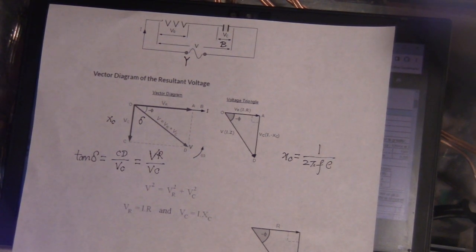Then what is a good capacitor? A good capacitor, based on the Nichicon data, is what? UFG is better than UFW. UFW 50 volt capacitor has 0.12, and UFG 50 volt capacitor has 0.10. That's tangent theta. What's tangent theta?